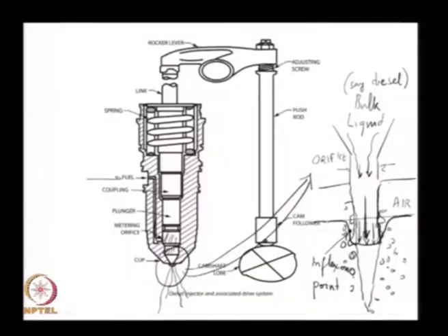There is an increase in the interfacial energy in this process that is facilitated by gravity in that particular instance. So, that is the source of energy. The faucet, which is my atomizer, is bringing them together in some sense, although it is a very trivial case to think of. But even in this instance, the atomizer is introducing the liquid in a way that the air can destabilize the liquid now and break the liquid up into drops.